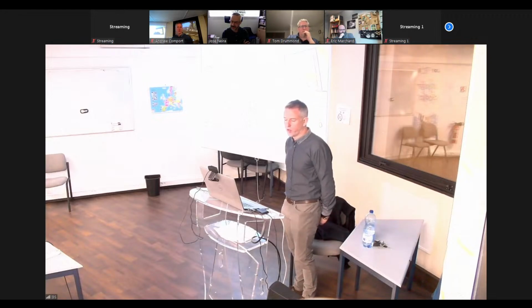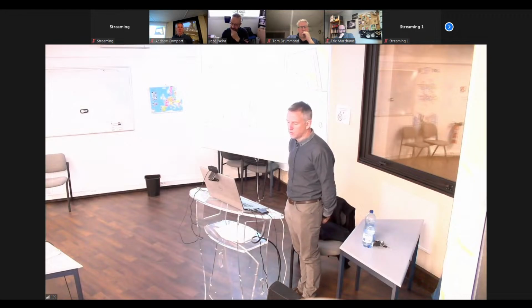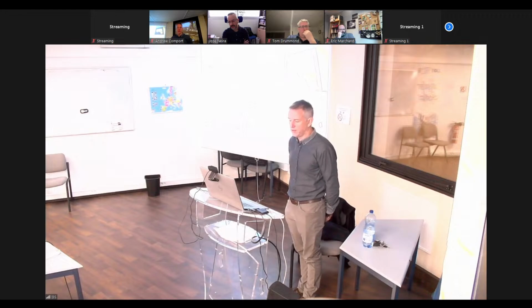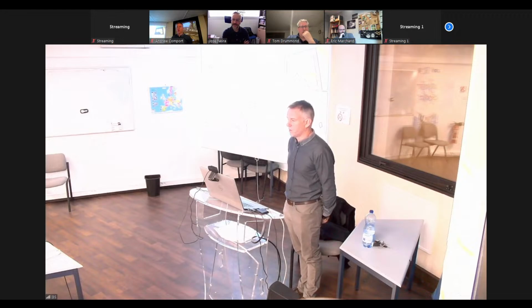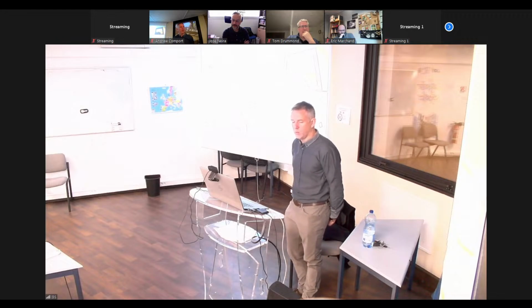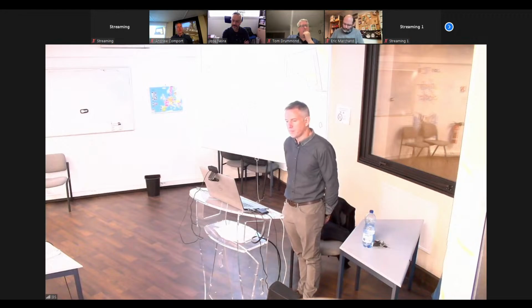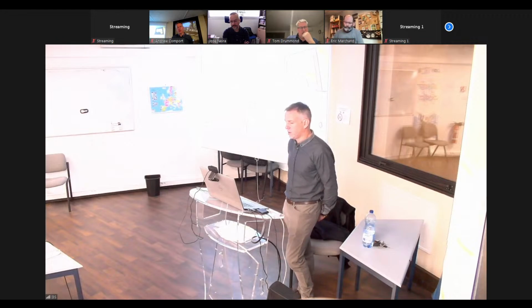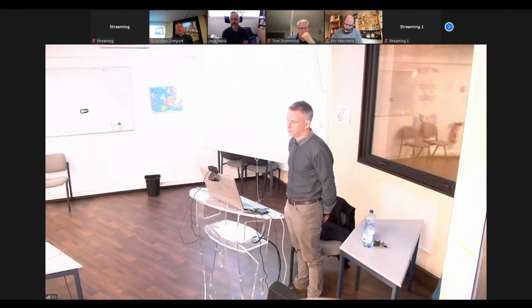Yeah, definitely. We were confronted with this kind of problem during the humanoid robot manufacturing project, where we created a map that we knew very well of the fuselage. We had all the semantics and everything working nicely. Then the day the European Commission came to evaluate the project, we had about 40 people standing around the robot and following it as it walked through the environment. We had prepared a bit for that. The way we did it was we didn't use the SLAM when it was cluttered. We would be open loop while looking for an uncluttered area, just avoiding obstacles until we relocalized and found where we were in the map. But that's definitely one of the big problems: cluttered environments. Yeah, so still a big problem.